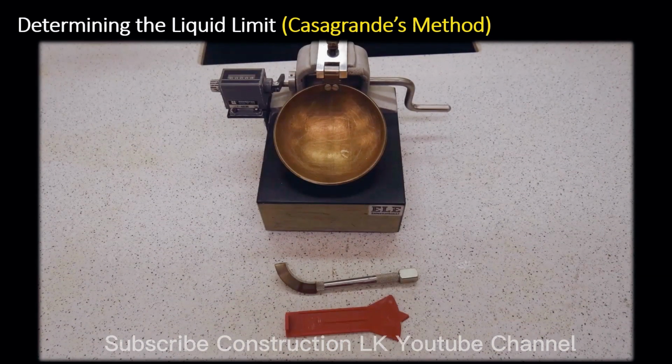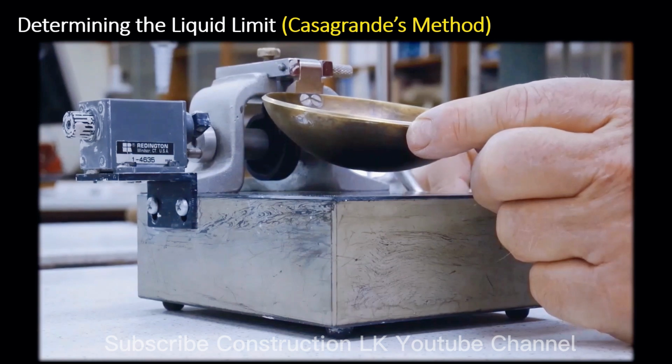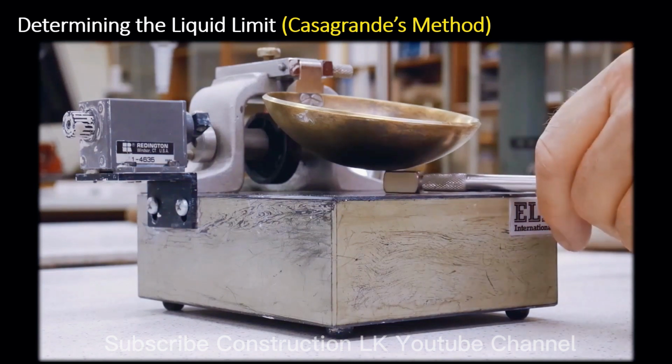First let's move on to the liquid limit test done with the Casagrande device and grooving tools. There are two types of grooving tools. One is for stiff material and the other is for soft. The two tools are set up to maintain the proper height of the material in the testing device. It will also give you a standard groove width. Before we start the test, we need to make sure that the device is calibrated for the proper drop height. We do this by using the back of the grooving tool, sliding it underneath the cup, making sure the lifting mechanism barely touches the cup.